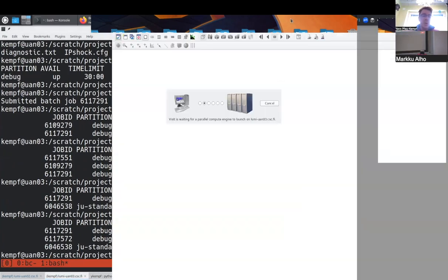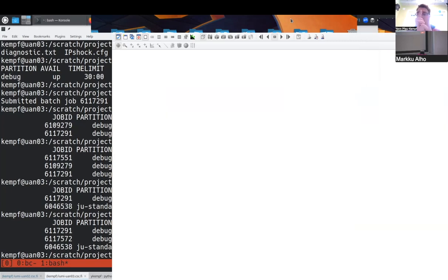It depends on the type of distribution you want to model. But the usual guideline is that, assuming you take a Maxwellian, which is typically what we have in the code as well, look at your thermal velocity and make sure that you have a sufficient number of cells, of sample points, across your thermal velocity, so the width of your distribution in velocity space. Now, what is sufficient depends on a number of things.